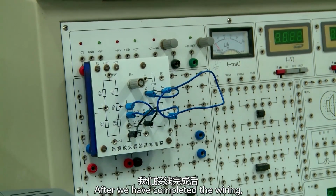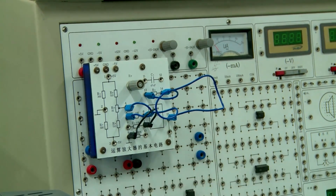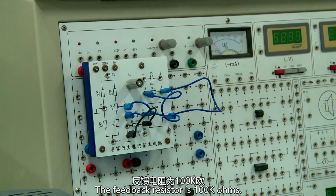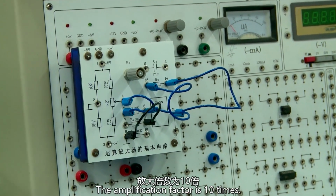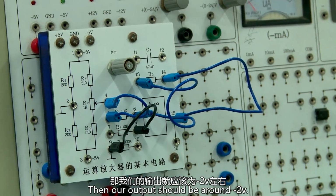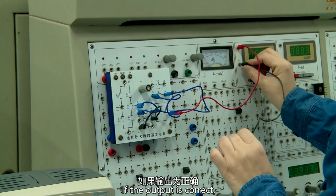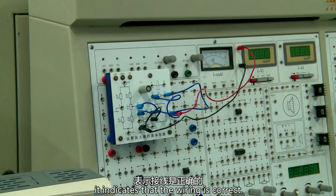After we have completed the wiring, how do we determine if the wiring is correct? Here, the input terminal resistor is 10 k-ohms. The feedback resistor is 100 k-ohms. The amplification factor is 10 times. Then our output should be around -2 V. We connect the digital voltmeter to the output of the operational amplifier. If the output is correct, it indicates that the wiring is correct.